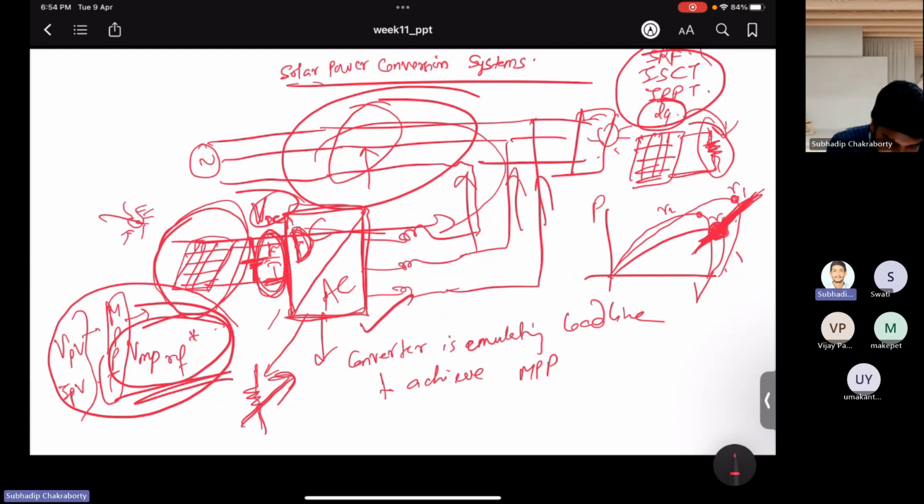It needs a converter, right? Another DC-DC converter. Otherwise, how will you impress variable voltage across the PV depending on the radiation? The controller will operate on the DC-DC converter, where you regulate the converter control such that its output is fixed, but the input is variable. The input is changed by changing the duty ratio of the DC-DC converter, which is sitting between the DC-AC and the PV.